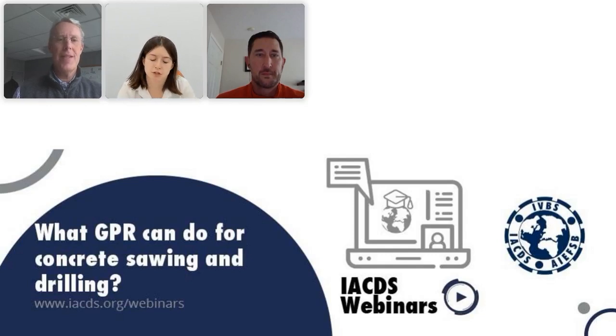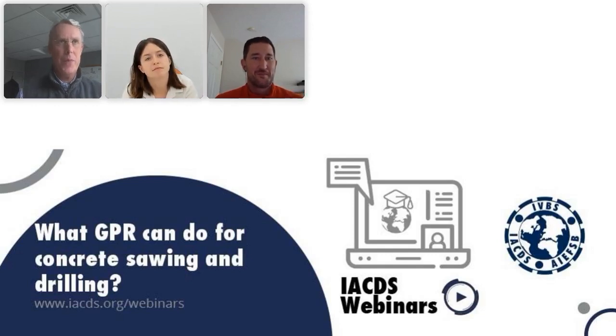Okay, and one question: GPR normally is purchased, or is it rented sometimes with an operator? Both. I think it's different in Europe than it is in the US. Many contractors who are building new buildings or renovating old buildings don't want to have to be an expert in GPR in order to know where they are telling their cutter to dig or drill or cut. And so they'll often simply hire a contractor.